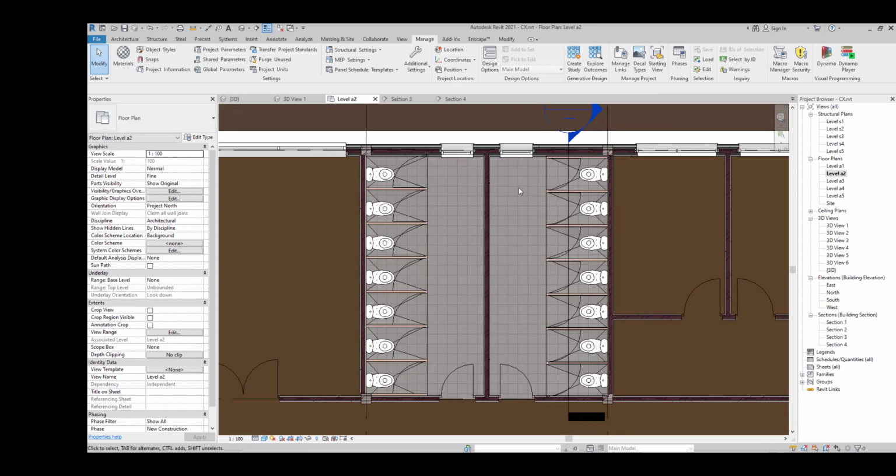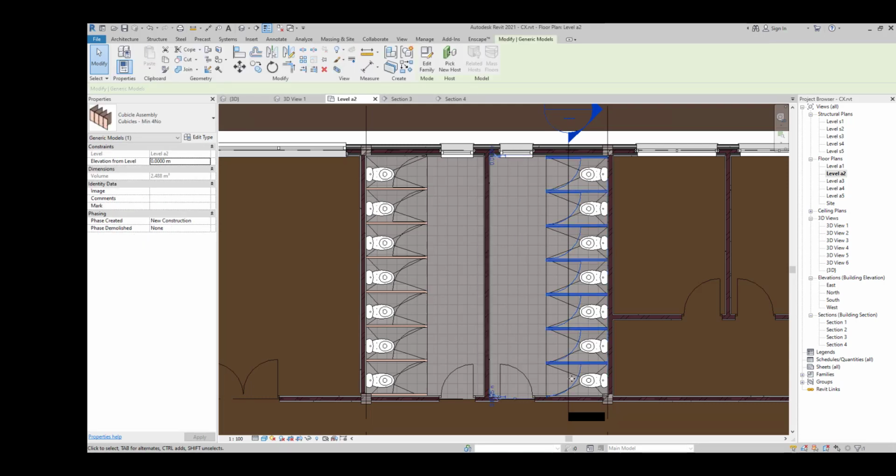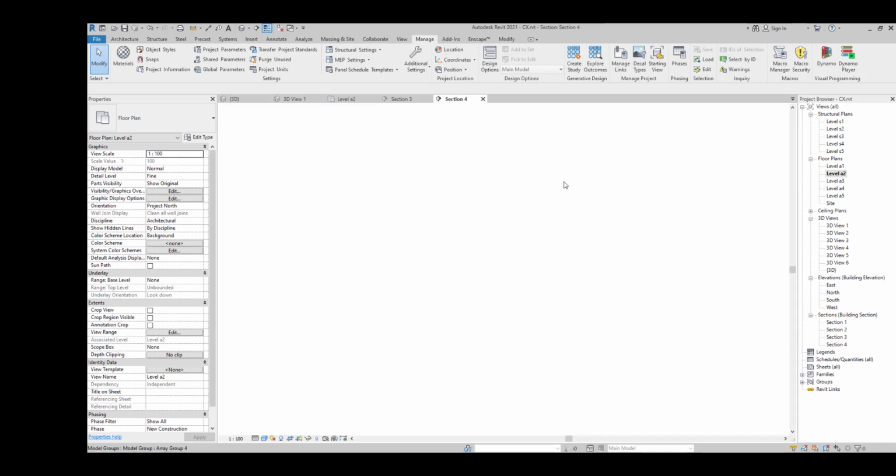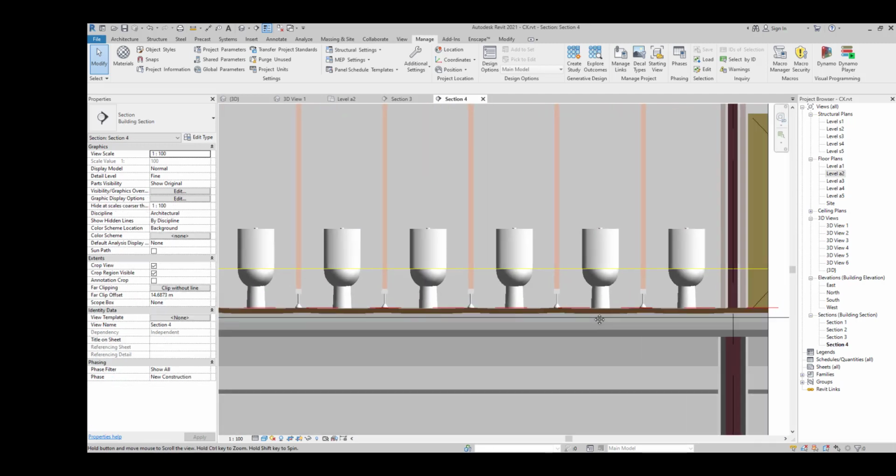So this is the way how we create the slope for our bathroom, how to place the partition for the commercial project, to place the toilet, to create the slope and separate material. Also how to adapt our floor without changing the structure by going to the edit type and clicking on variable. So this is the process we need to do, and it's going to be very well done, finished.